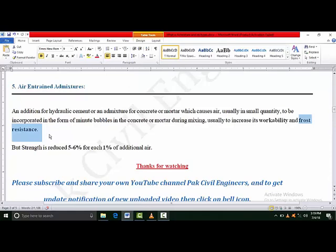And the cement material slips on the minute bubbles, due to which it becomes more workable, as well as frost resistant, with freeze and thaw resistance, okay. But strength is reduced by 5 to 6%. So this is the side effect of using these types of admixture: it reduces the strength by 5 to 6% for each 1% of additional air, okay.